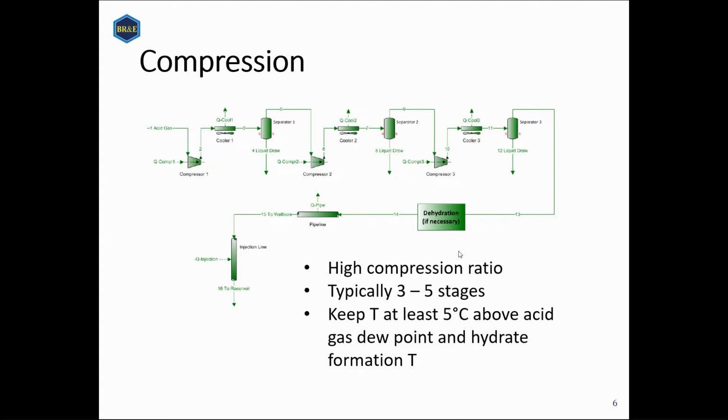If you try to keep the stages lower, then your compressor outlet temperatures are going to be a little bit too high. Your compression efficiency is going to be a little bit lower. Trying to compress a hot gas is a lot harder than trying to compress a cooler gas.